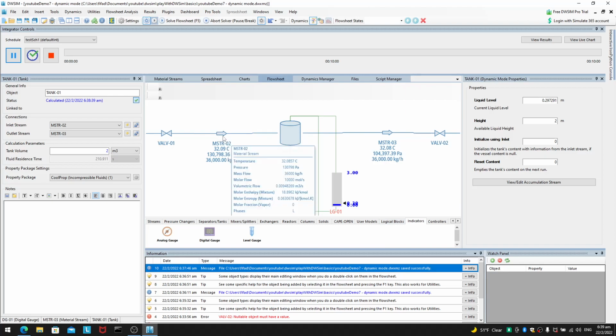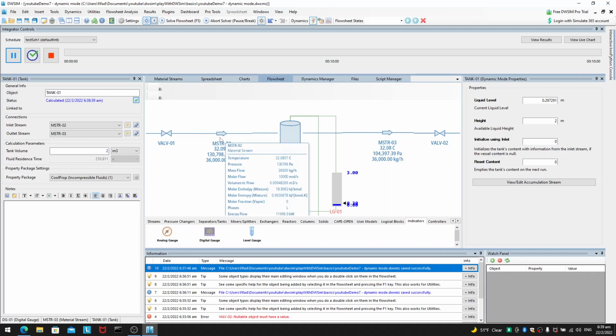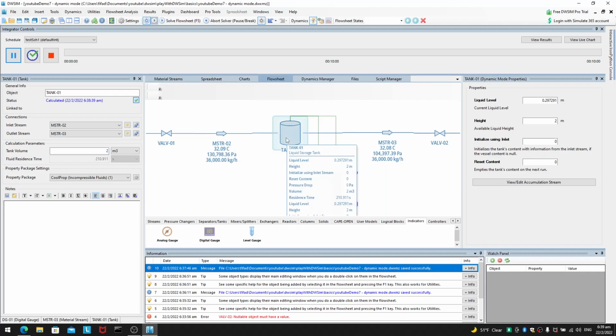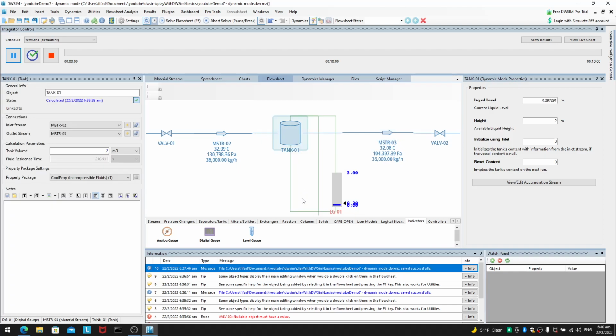And of course all the pressure here will disappear. I guess it will convert into kinetic energy in this tank, and then the liquid will just slosh around a little bit after it stops. Okay, this excess pressure is just lost. And the only pressure within this tank is 0.297 meters. So that's 0.297 meters of head, which will give this stream slightly higher than atmospheric pressure. Alright, so this pipe is likely towards the bottom of the tank, and then the tank is exposed to atmosphere.